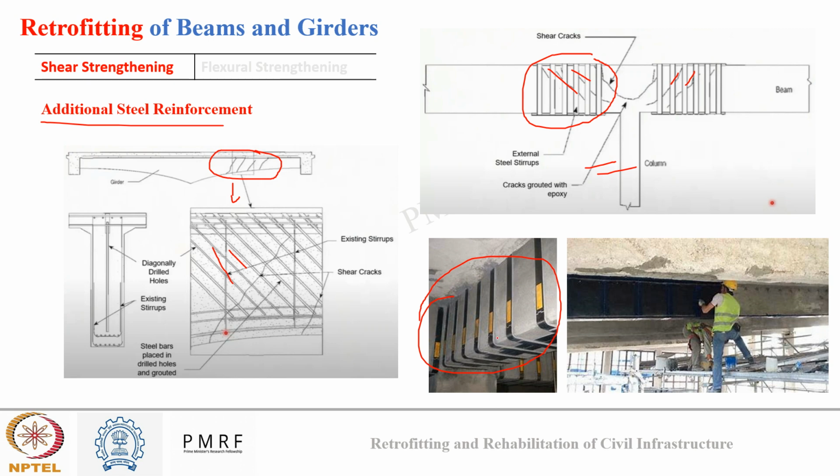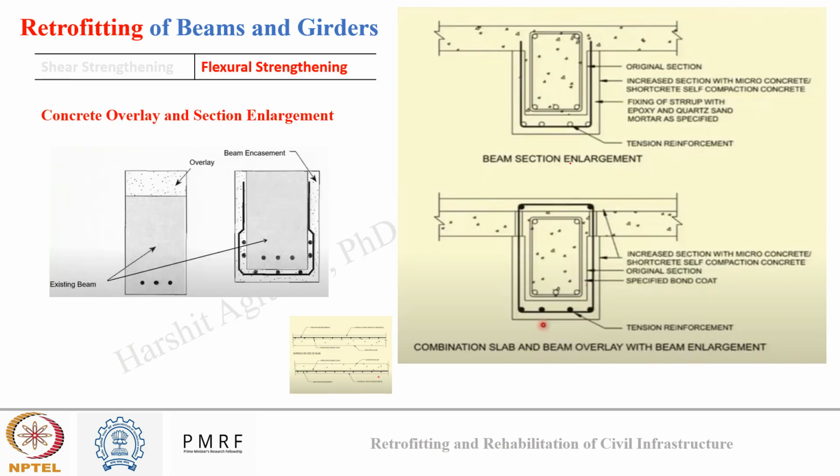Here, at the bridge deck, you can also see horizontal steel plates installed for strengthening against shear force. After shear strengthening, the second is flexural strengthening.